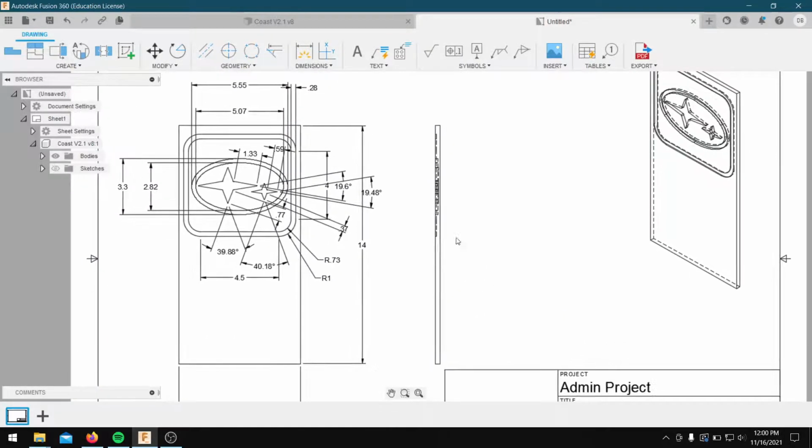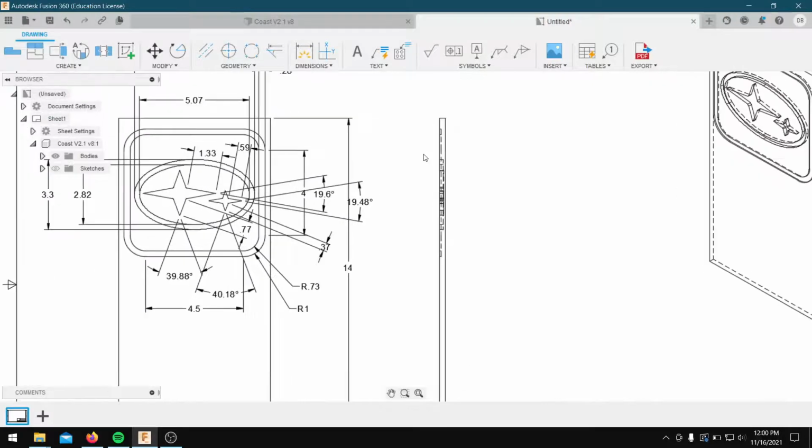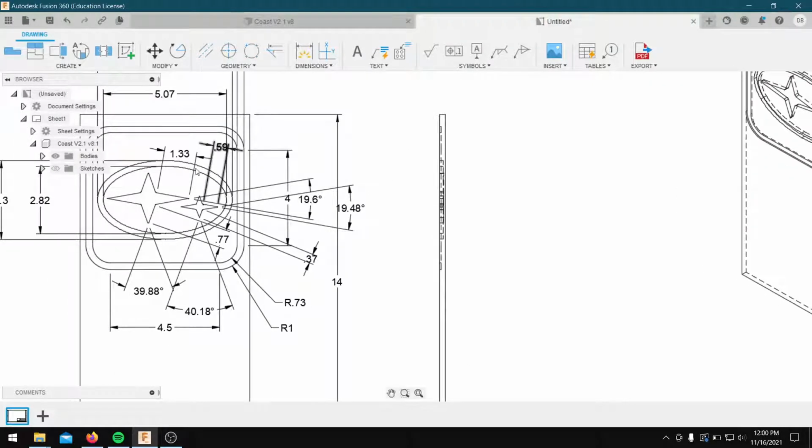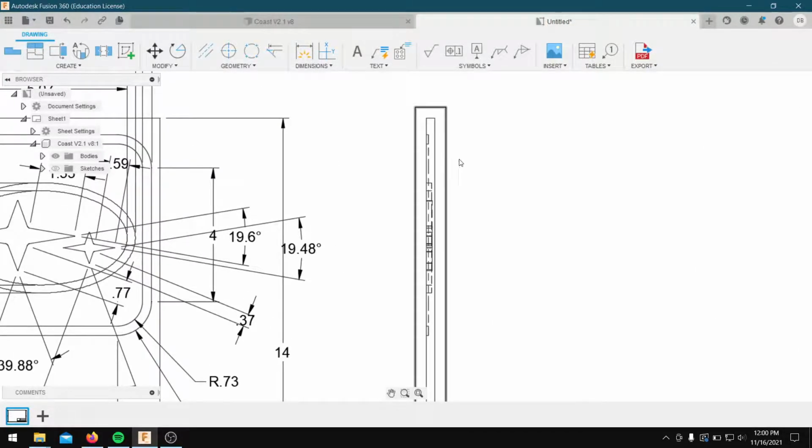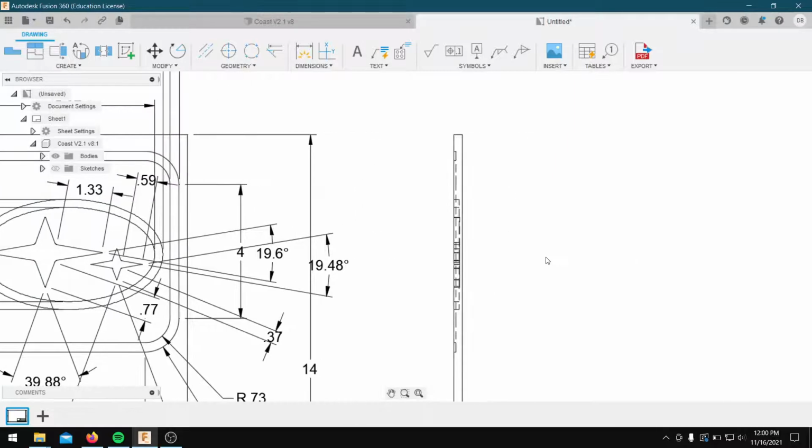And so the next part is we have this edge view. Essentially the edge view is most useful for knowing the thickness of our stock, which is 1/4 inch, and knowing the depth of cut. Since I have different kinds of cuts, the Laguna needs to know how deep these cuts are. So I need to make sure that these cuts are dimensioned for anyone who may potentially want to recreate this in the future. They need to know how deep to make the Laguna cut.